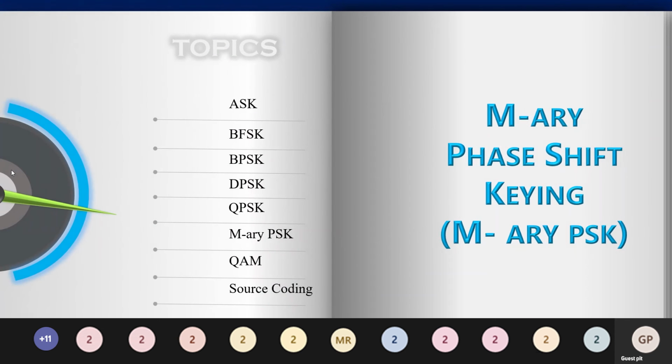So the next topic that we're going to see is M-ary. For BPSK, the data that we have taken, the bit duration and symbol duration TS is 1. QPSK, DPSK is an advanced version of QPSK. There is no separate need for a carrier. Whereas for QPSK we have clubbed two bits to form a symbol TS. So M-ary means M number of data that we can form a group, we can form a club. It may vary, like 4 PSK, 8 PSK, 16, 32, 64, in this manner it will vary.